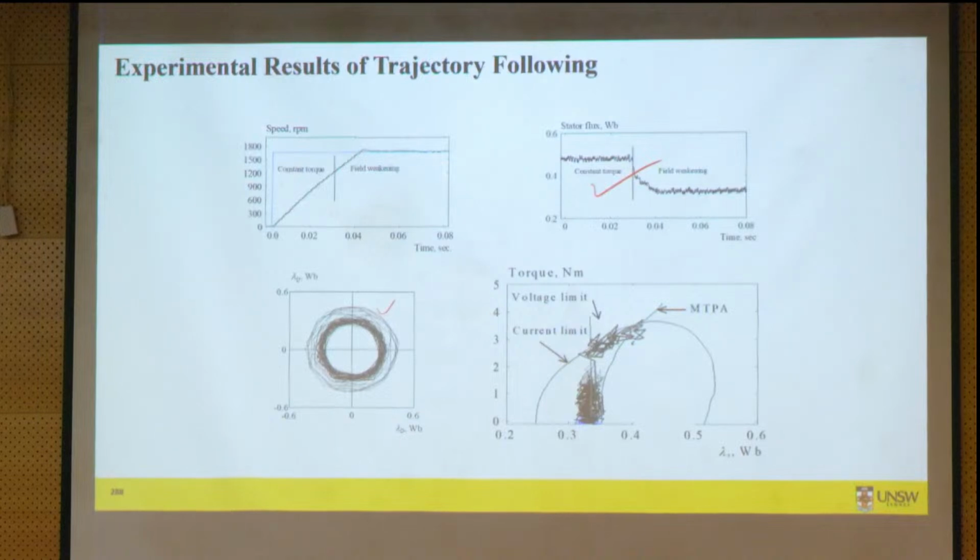Theoretically, we should see that, but it's not the case. And this is the reason why DTC is problematic, because you see a lot of this. There are high frequency harmonics as well. That means your flux linkage has ripple, and that translates to ripple in your torque. So you get high torque ripple and high ripple in your flux linkage, causing your motor to not run smoothly under DTC with a switching table.